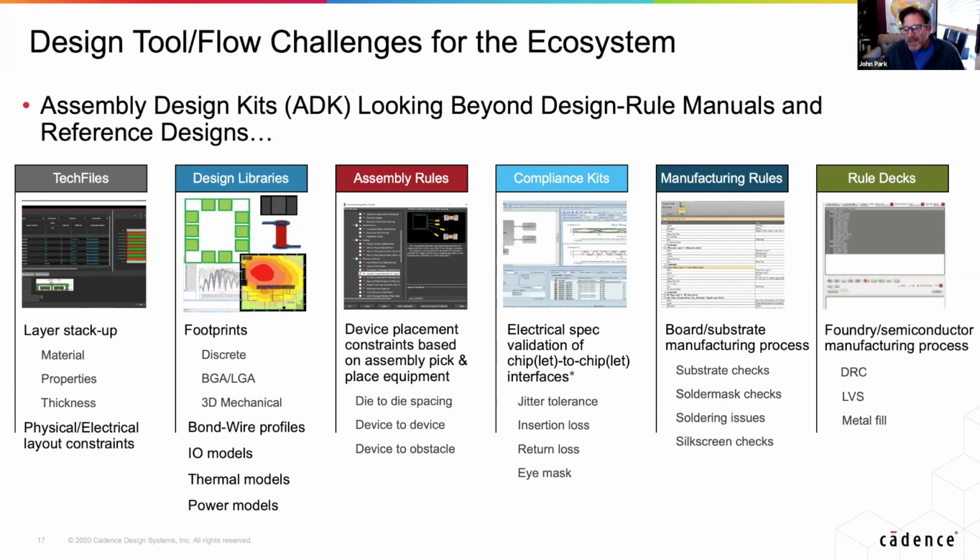And then the last two things here, rule decks, that's pretty common in the world of semiconductor design. It's brand new to the world of package design. We'll talk more about that. What we're used to in the package design world are more manufacturing rules, because we typically go out to board houses because we're designing laminate substrate.